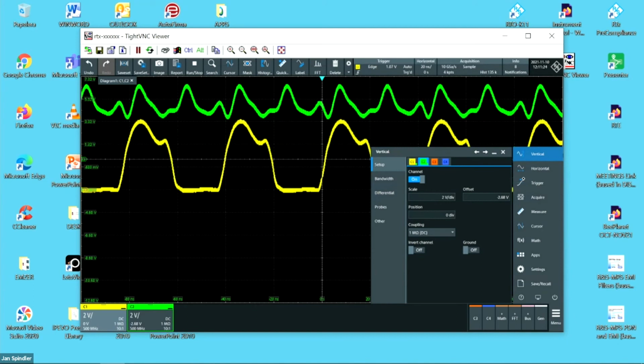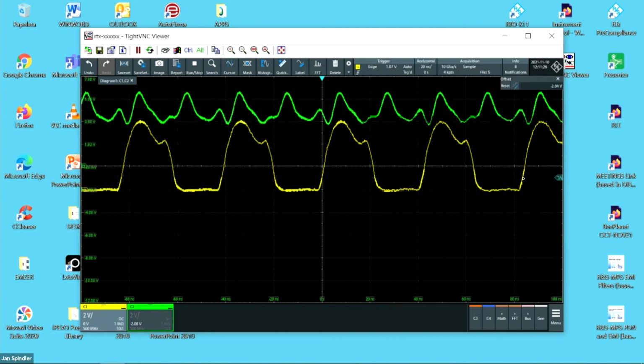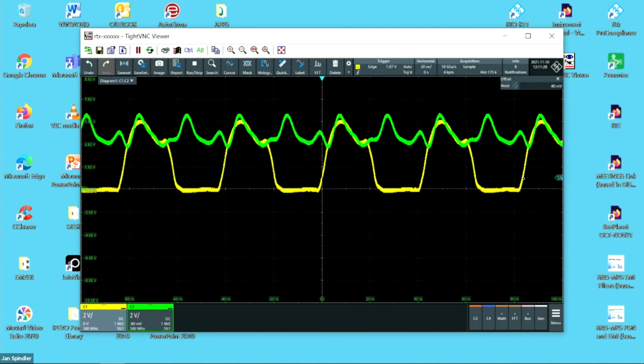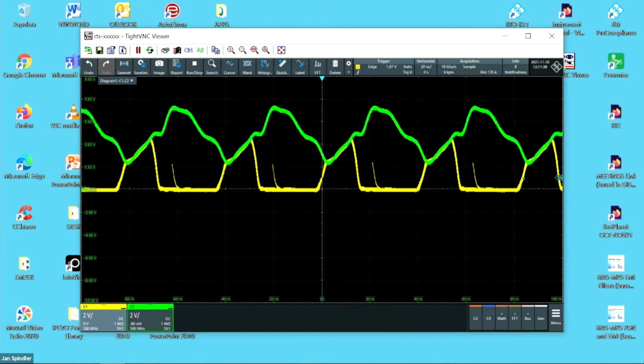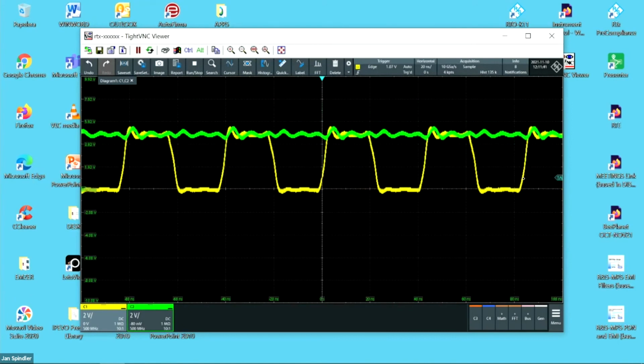If you move up and down this trace, you will see that the envelope of the output of the integrated circuit is following the changes in the power supply. If we introduce the decoupling network, this is the result. The power supply is constant, and the signal integrity is recovered. And now I am not radiating. At least I am radiating 15 or 20 dBs less than without the decoupling network.